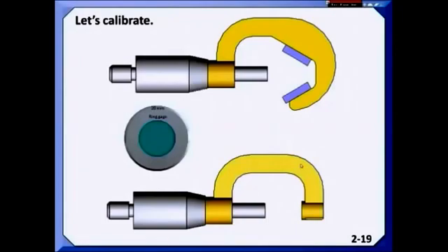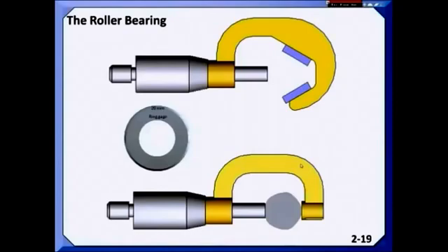we calibrate our ring gauge at 20 millimeters and our anvil mic and our 2-point micrometer. We then bring in that 5-lobe part, which is very common in centerless grinding, 5 and 7-lobe parts, even 3. And we show how, no matter how you mic that bearing, you could not detect the lobing effect. And even if you put it in the anvil mic or tri-mic, as you rotate it, the mic would not change. But if they had followed Rule 1 and checked the perfect form at the maximum material condition, they would have found that that had a lobing problem.